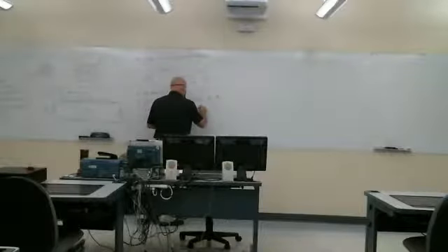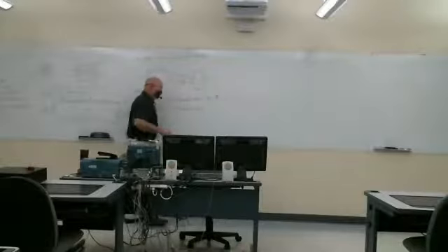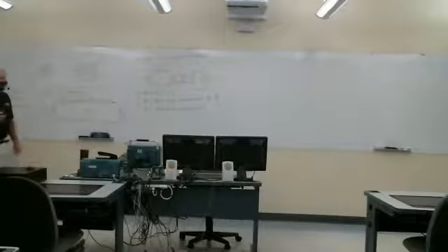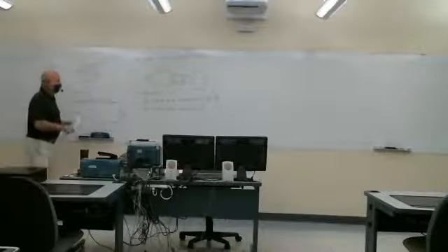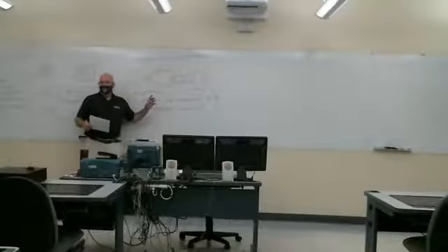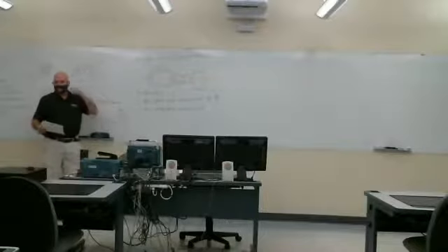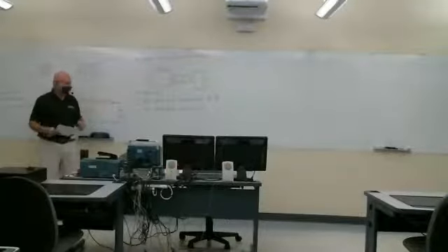The attenuation constant, alpha, has units of meters to the negative 1 power, or 1 over m. This is going to appear as an e to the minus alpha z. So this represents a change in amplitude down the line. Take the length of the line, multiply it by alpha, then that change in amplitude is e to the minus alpha z. It's an attenuation, implying that the output amplitude is going to be smaller than the input amplitude, due to resistance in the line.